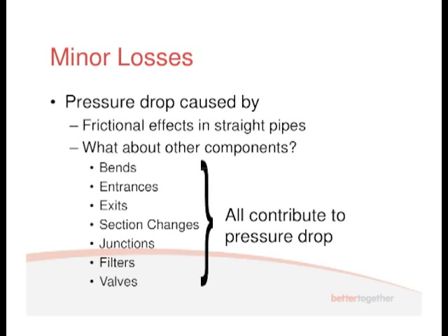Filters, okay. And of course the big thing is valves. And valves we put in pipes to give us a deliberate pressure drop, okay. When we want to turn the tap off, okay, that's a valve. And you want to slow the pressure of the water coming out, you turn the valve down, that causes a pressure drop. And that's exactly what's going on here, okay. And so valves, you get a value that will influence how much the pressure drops are, okay?